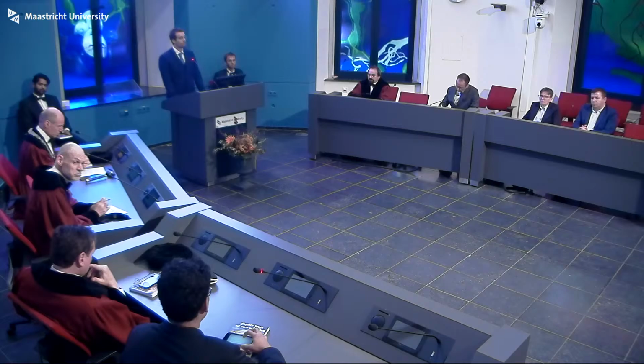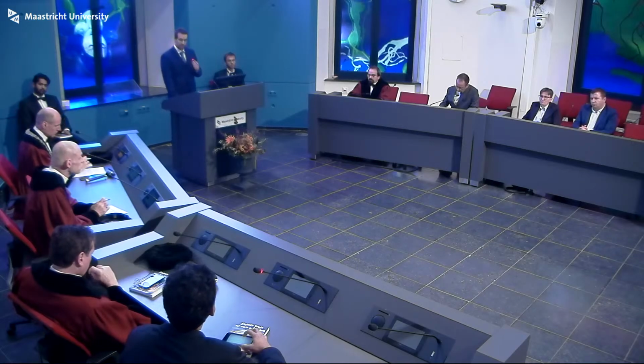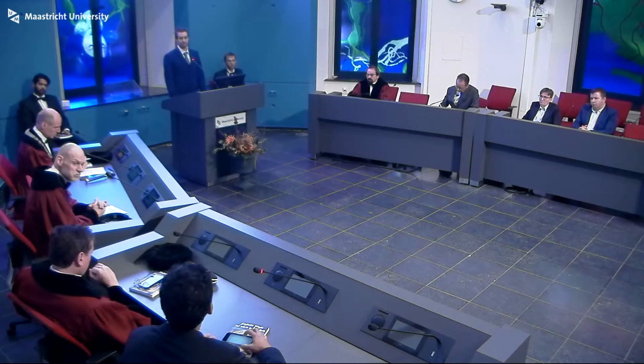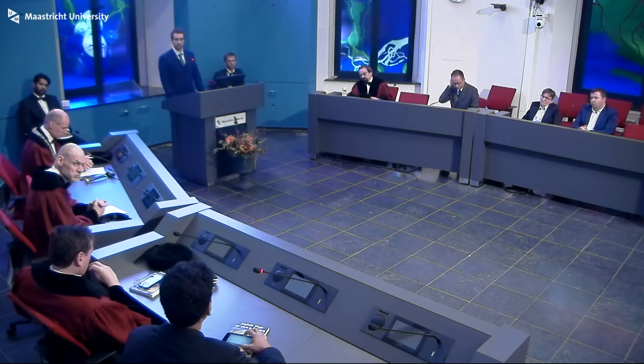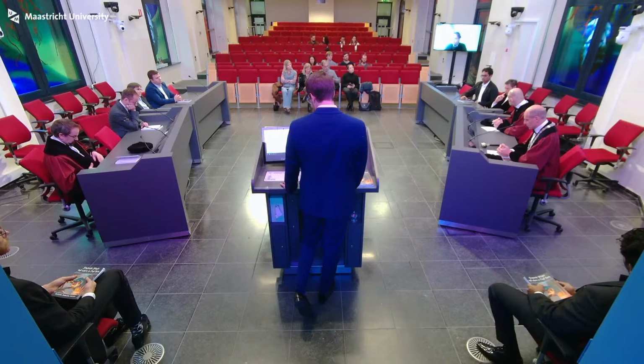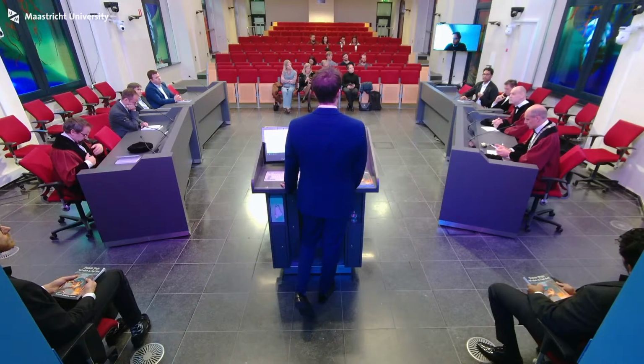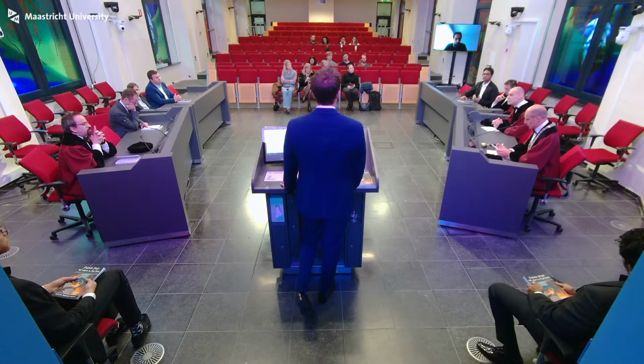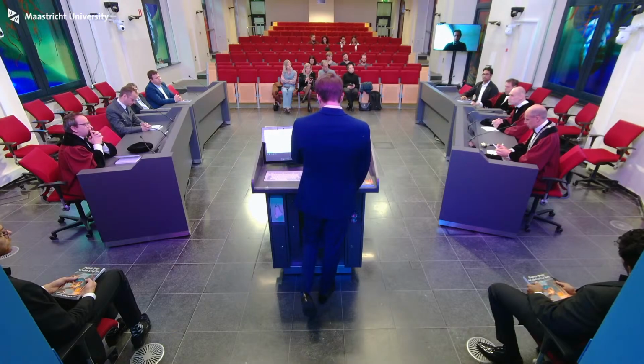Okay, thanks. And then one final question. So you talk about the printability window, and you say that if you measure the viscosity and the thermal characteristics using DSC, and know the machine geometry, you can work out all the printing parameters. But I did not see a conclusion whether you can find a printability window for every material, or are there some properties that will make printability just inaccessible? And how from your model can you find these?